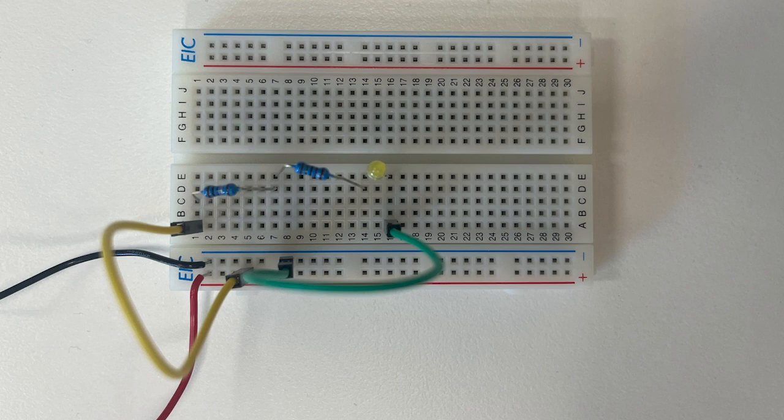So what are you trying to measure right now? The breadboard or the LED? Oh, no, you're not going to be able to do it on that one, unfortunately. That doesn't have diode mode. Oh, yes, it does, sorry. So we just have to flick that one up to the top there with the diode. Now try again. Try flipping the probes. Just switching around, because one will be positive, one will be negative.